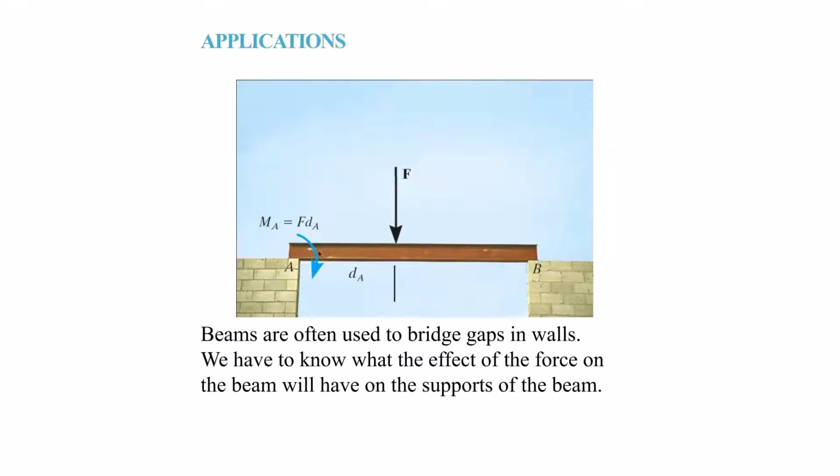If we assume the beam has negligible weight compared to this force, we can neglect it, and for this simple example we'll think about it that way. So you have some force acting up here and some force acting up here, and those are considered to be the reactions. If we're thinking about this just as a summation of forces, we would have two variables, a reaction here and a reaction acting up here. So we would have one equation and essentially two unknowns.